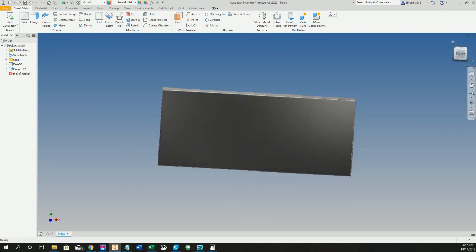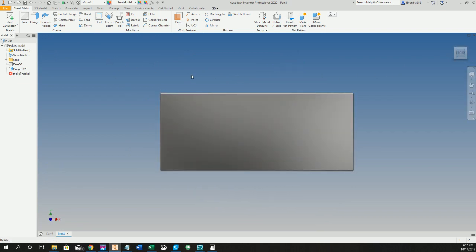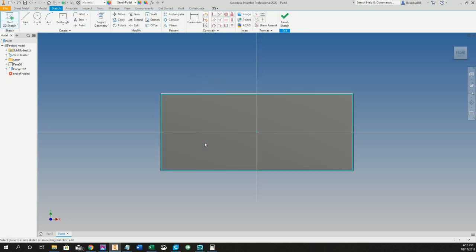So let's go ahead and place the knockouts next. I'm going to click S for sketch, click on that face, come back up underneath the sketch, rectangle, and I'm going to draw two generic rectangles. First thing I'm going to do is make sure that my view is the front, word is horizontal. I'm going to click on vertical. I'm going to pick on the center point of that rectangle, and I'm going to pick on the origin point because I want that centered right over the top of 0, 0, 0. That way I know that these little cutouts are right dead center of this pan.